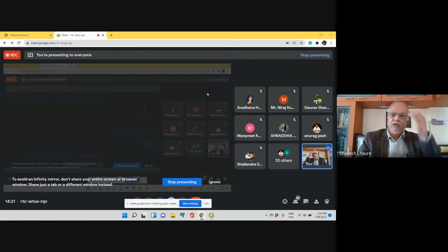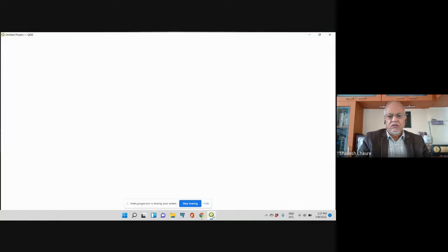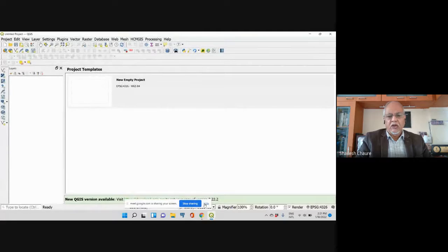Okay. So for this, we have to use the functionality which is available in QGIS. So I was telling that we can add the data through add vector layer or add raster layer, because we don't have any vector data with us, but we intend to create such data. And for creation of such vector data, we need some base map.